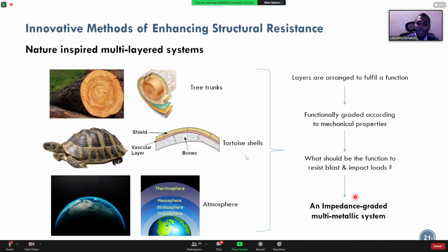You need ductility basically. Enhancing the reinforcement in reinforced concrete is a way of enhancing the ductility. And generally, the expectation is that you let the structure deform because there's a high level of kinetic energy that is exerted from the blast onto a structure. There'll be a lot of strain energy that the structure will have to undergo. So you have to let the structure deform. When there's a significant energy, you need to let it deform. So if you want it to deform without failing, then you need the ductility, because if not, it's brittle. You will basically have catastrophic failures, right? So ductility plays a significant role.